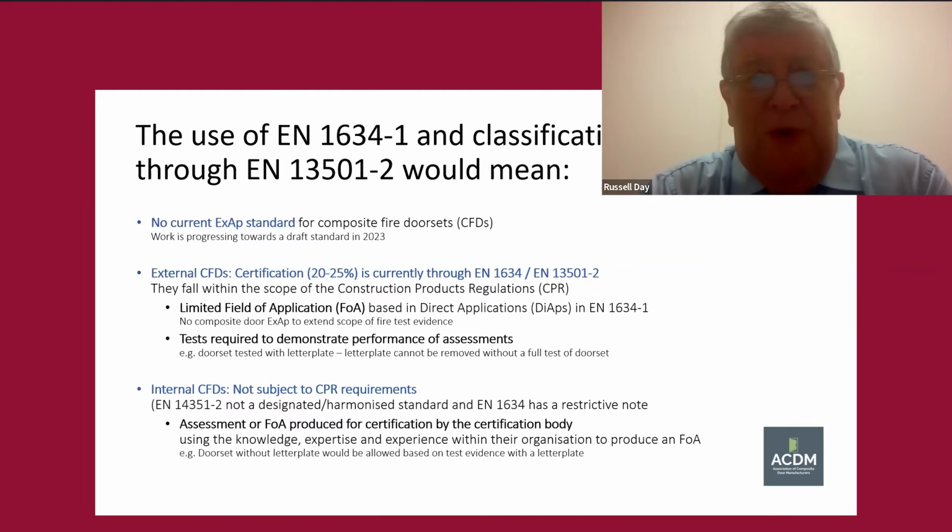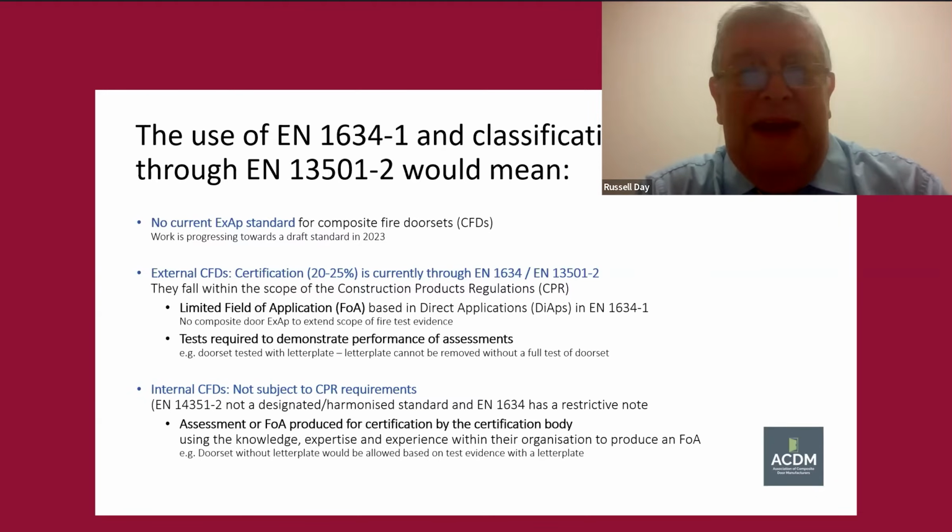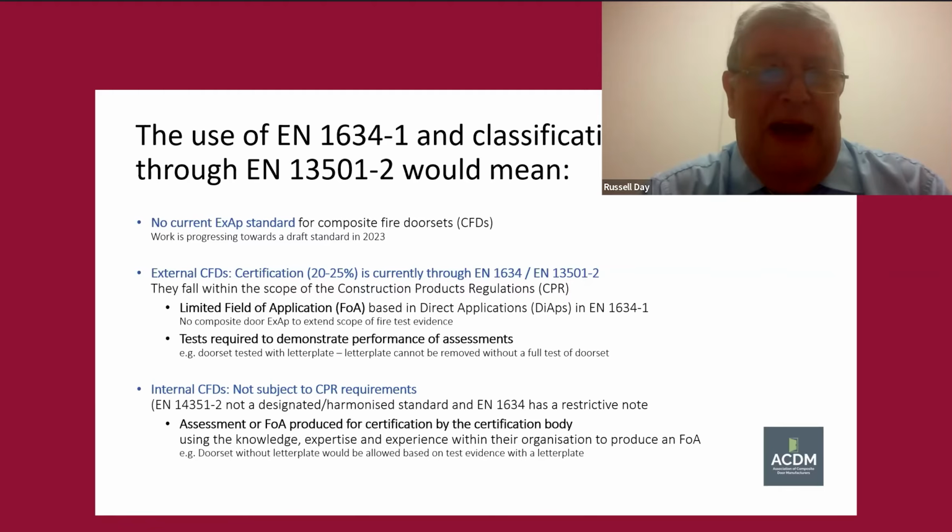This is so important because 1634 Part 1 testing results are of no use until they are classified through EN 13501 Part 2. And EN 13501 Part 2 also provides a field of application for the product. As many are aware, most fire resistant products need an assessment of some sort to extend the application of the results of fire testing.